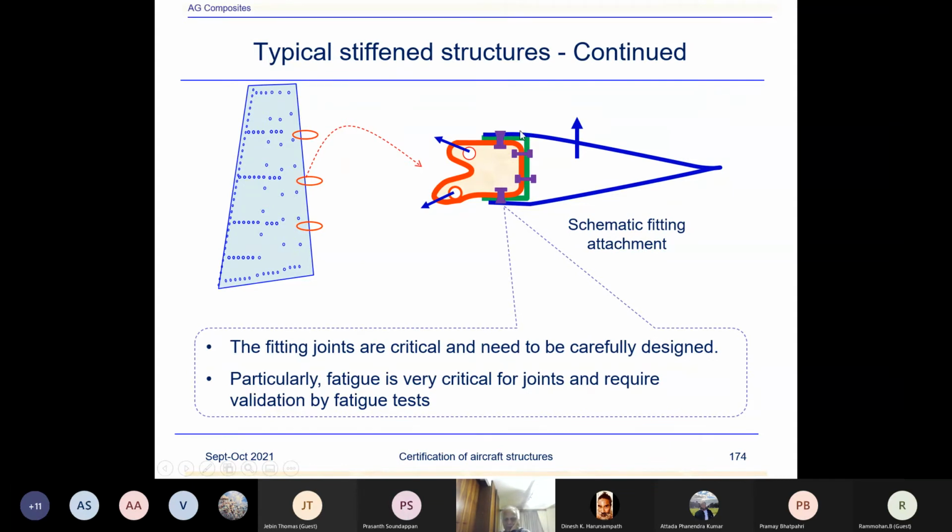Okay, and now one of the problems with this is, when you are doing the design of these joints, say a laminate composite, another laminate, and a metal, there could be some other shims. Shims normally degrade. This also acts like a shim. Load is transferred directly from the metal fitting to the skin mainly. The spar picks up only very little load. So basically the bending moment is high on these fasteners.